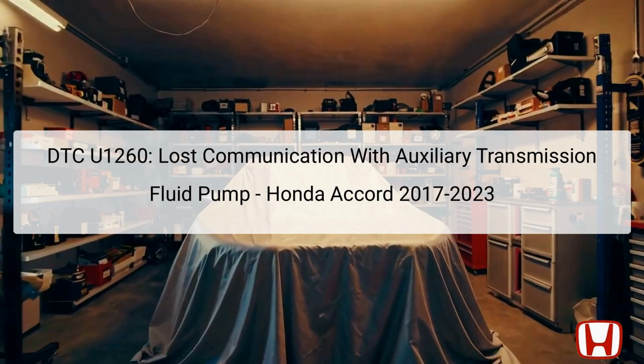The auxiliary transmission fluid pump is crucial for maintaining optimal transmission fluid pressure, enhancing performance and longevity. Its location is typically near the transmission assembly, connected with a 4-pin 4P connector to the transmission control module, TCM. When this DTC appears, it usually signifies either a failure in the electrical circuit that could disrupt communication between the TCM and the fluid pump itself, or that the auxiliary pump might be malfunctioning.